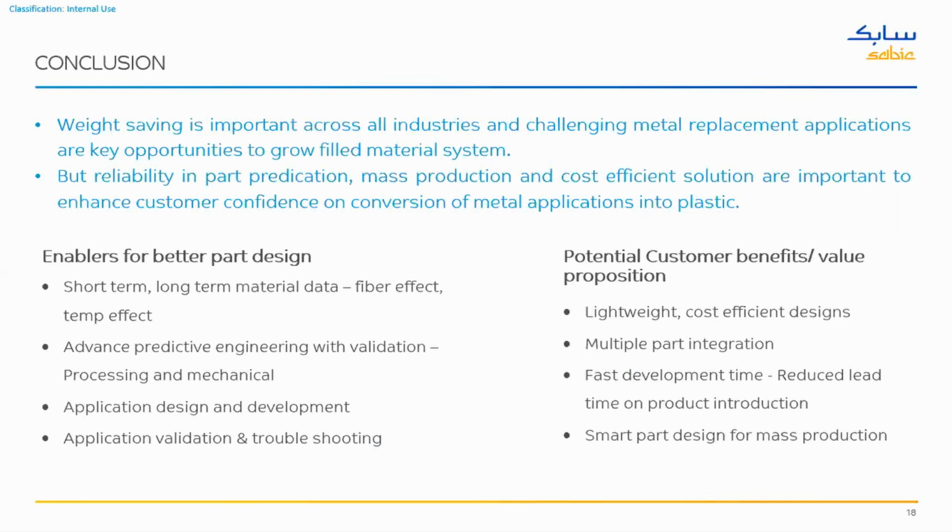One is to understand the right material behavior as a function of fiber orientation, as shown with those shear plaques with the 0, 45, 90 orientation samples, how the material stress-strain curve changes as a function of that. So it is very important to understand that. In fact, we have also done the study at different temperatures, so understanding the temperature effect is important too. And OEMs are looking for short-term and long-term material data.